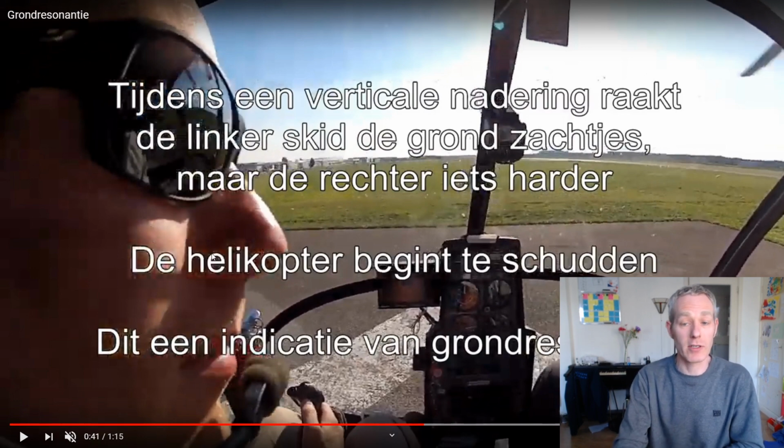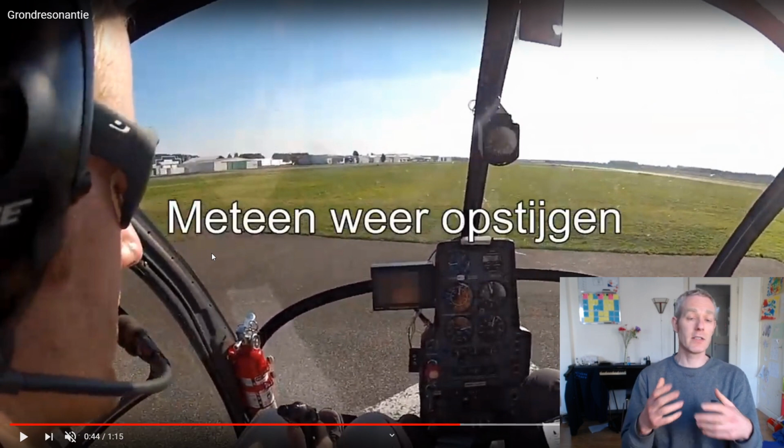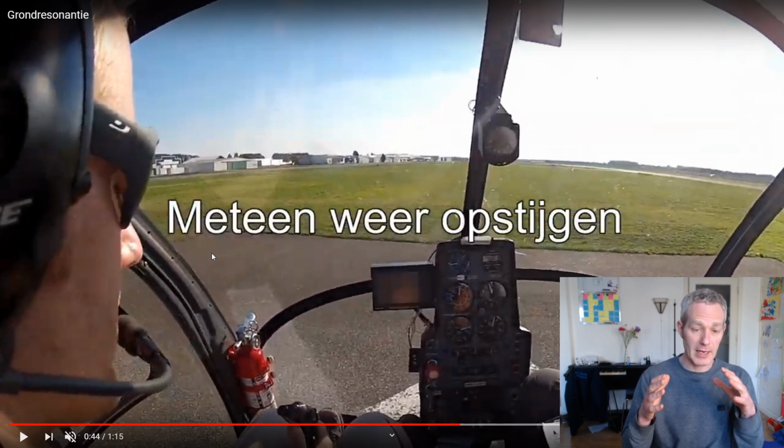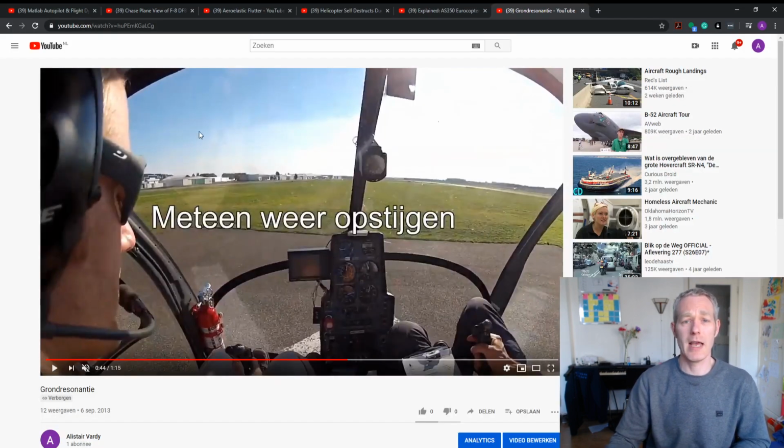Luckily, I had my instructor next to me, and the wobble gets bigger, and the solution, if there is no problem with the helicopter, is just to lift off. Then the resonance in the landing gear stops because there is no ground to push against. So luckily that can happen as well.